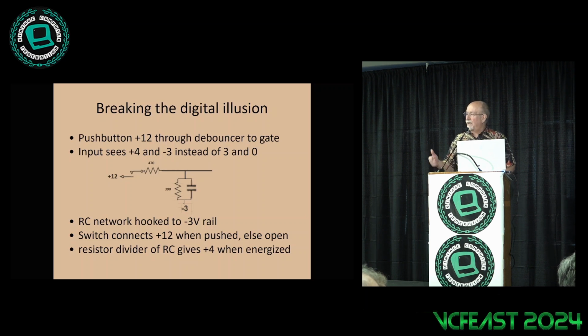So you have to do this to understand some of what you see, to debug what's normal and what's not. And to realize that these gates are enormously resilient, because -3 is just fine to send as a logic level 0. Anything that'll pull that through that diode current down to turn on the next one as a 0 is fine. So -3 is as good as 0. +12 is as good as 3. The only limit is, for the plus side, what voltage is so high the diode breaks down. So there'd be a real high one, but impractically high. And the only limit for -3 is how much current you pull through it.